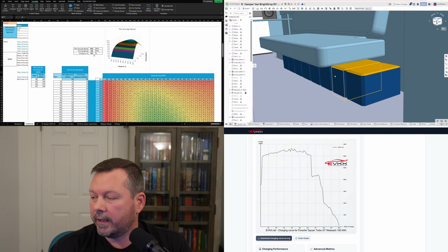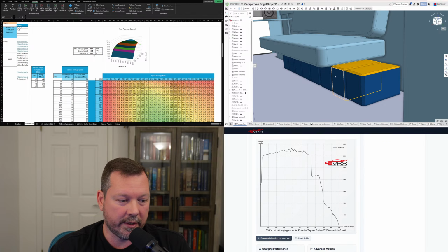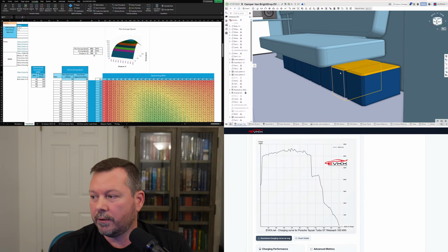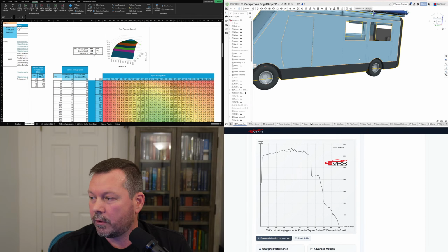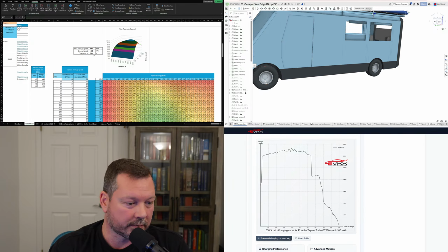And then it would be lithium iron phosphate. So that would be safer, but still if it was a fire risk, you could kind of enclose it in a box that's semi-fireproof and resistant. And then on the wall, the camper, have that be the weak point where it would vent. So if something did go wrong, it would vent outside of the van and not into the cab.